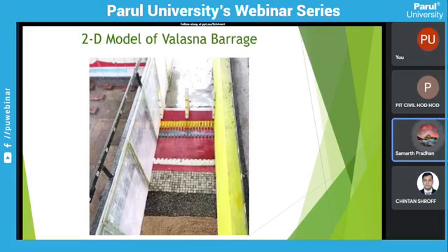See here, you can see this white portion. That end sill was previously on the border of the stilling basin. But when we ran the model, due to that end sill a secondary hydraulic jump was created. Immediately, the project officials, design officials and Gary people were also there. They decided it was needed to shift the end sill, and the decision was taken immediately to shift it 6 meters away from the end. So this white portion is 6 meters away on the stilling basin.